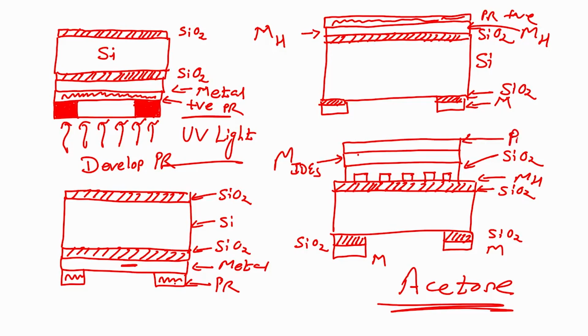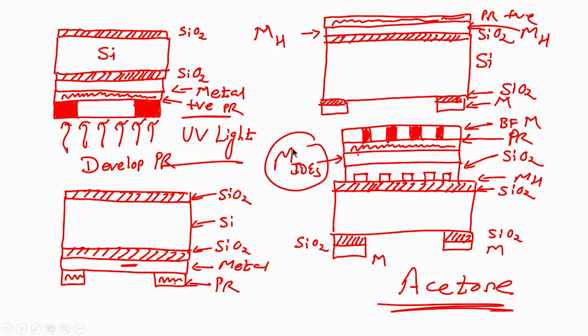will spin coat photoresist. Then what you have to do? Pre-bake at 90 degree. Then what you have to do? Load the mask. This mask is for patterning the metal for interdigitated electrodes, this is my bright field mask for patterning the interdigitated electrodes, right.